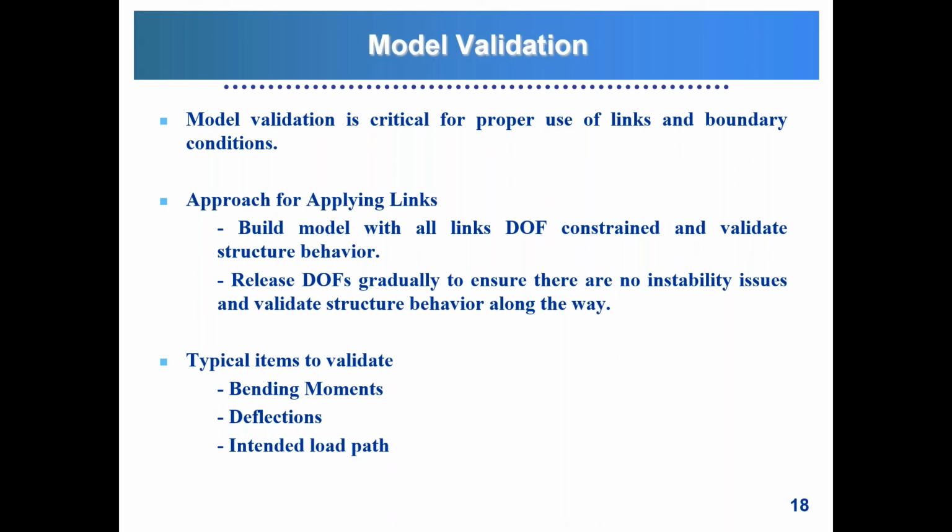Same thing with deflections. Look at the deflected shape, see if it makes sense. Look at the actual values of deflection that you're getting. If you have a 100-foot simple span bridge, and the deflected shape looks good, but then you look at the values and you have like 10 inches of deflection, obviously there's something wrong with that.